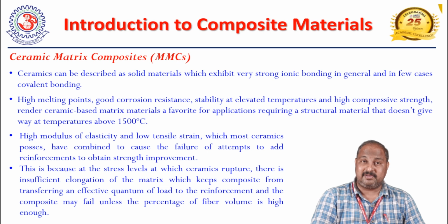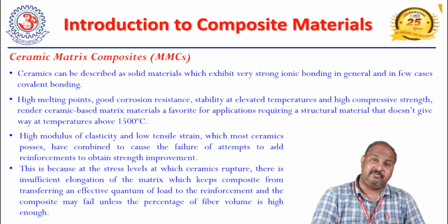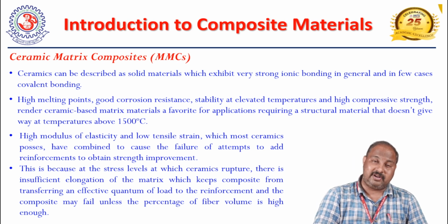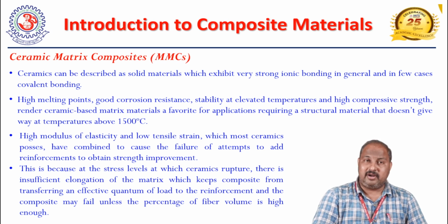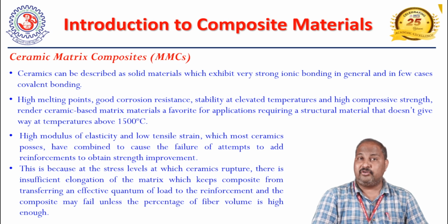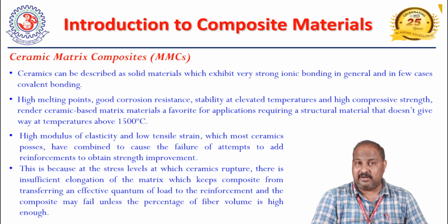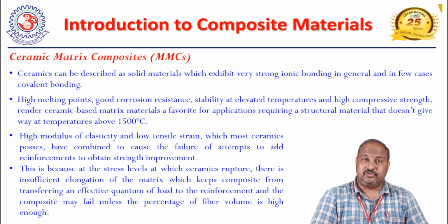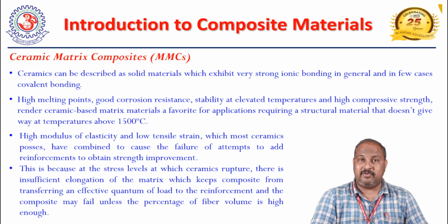changing the failure mechanism can be connected here, where in the CMCs brittle failure is going to occur, that is, the ceramic matrix having a brittle failure mechanism, which can be transformed from brittle failure into semi-ductile failure or nearly ductile failure. We can improve the ductility of that material, so it is not completely brittle. That is the reason we can use these CMCs as structural materials.